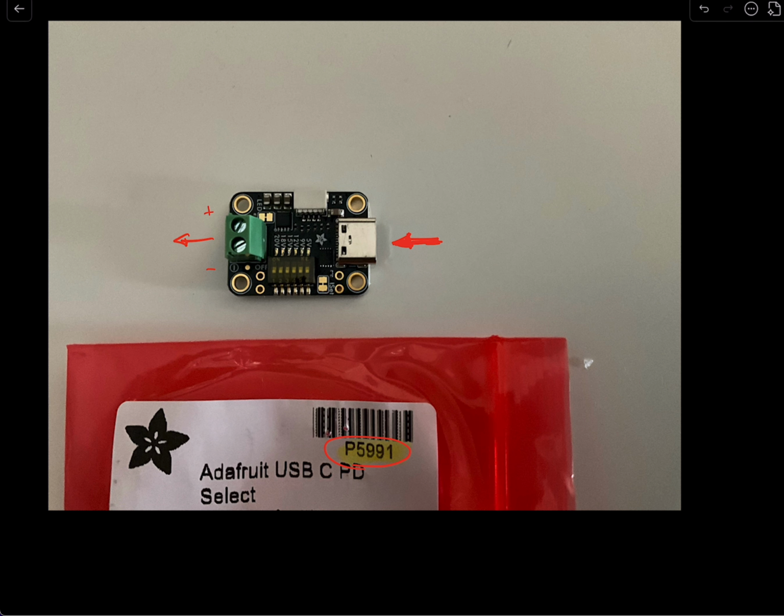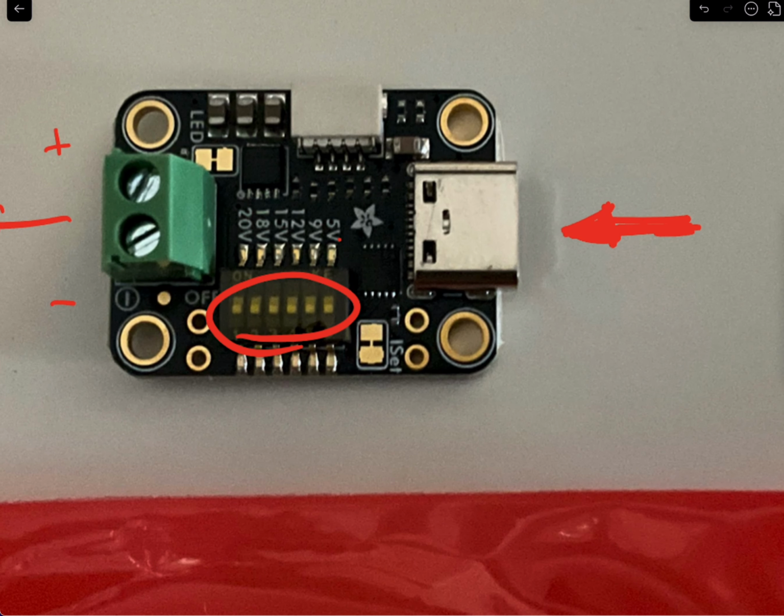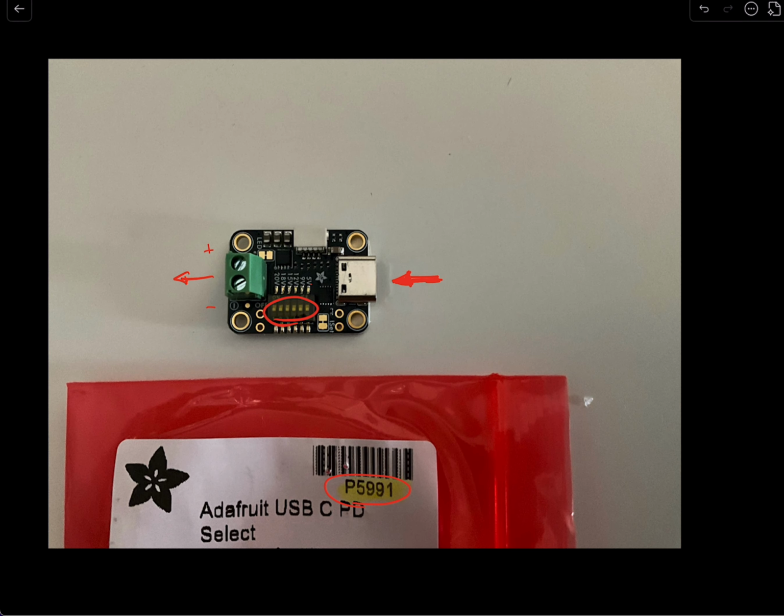and you can determine what voltages you are going to get in 2 ways. One is by flipping this micro switch that we see here, and then that allows you to say, well, give me 5 volts, 9 volts, 12 volts. We can actually see those voltages there, right? But most importantly, you can have any, let's say, Arduino code, and these people provide you the libraries and the examples and all that. So you can have your Arduino C++ program basically asking this power source, okay, show me what you are capable of. And that's a very good way of validating that the power source that you have is that good.